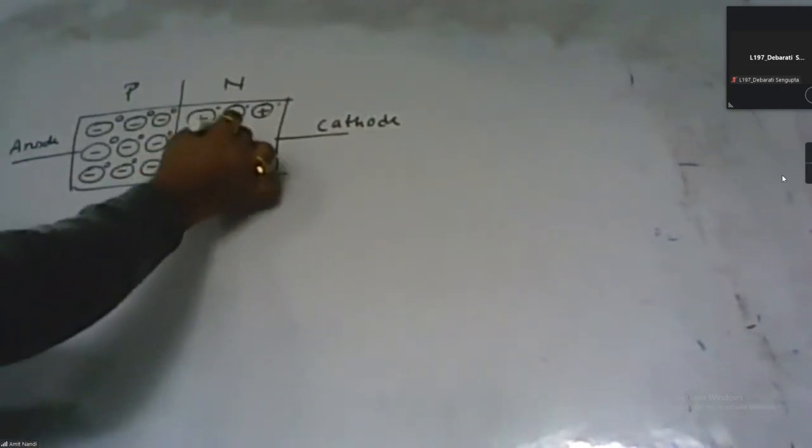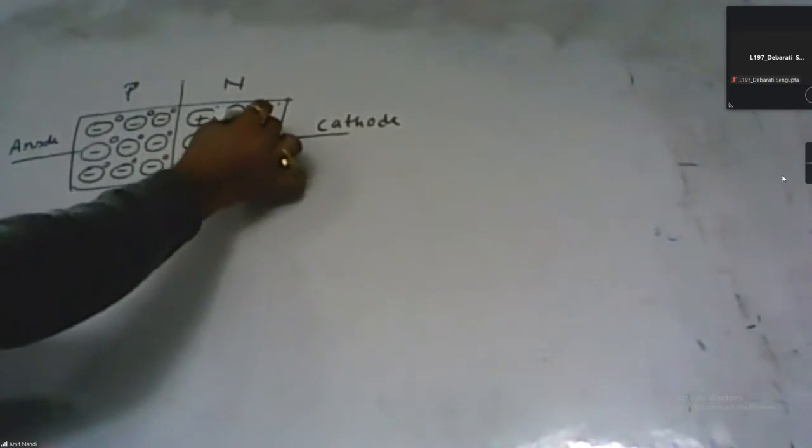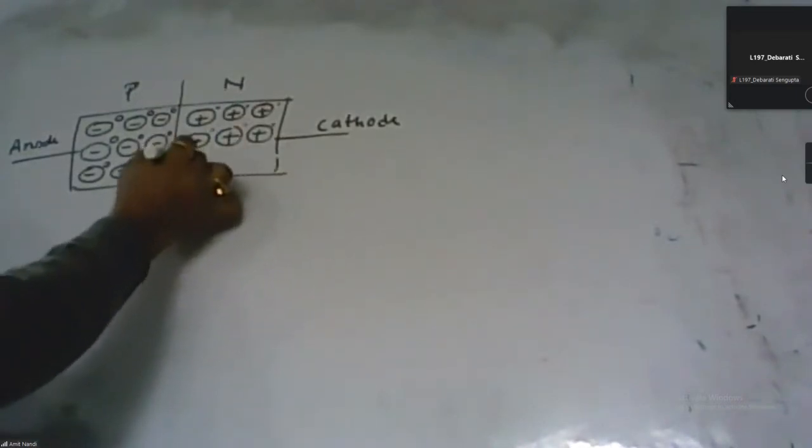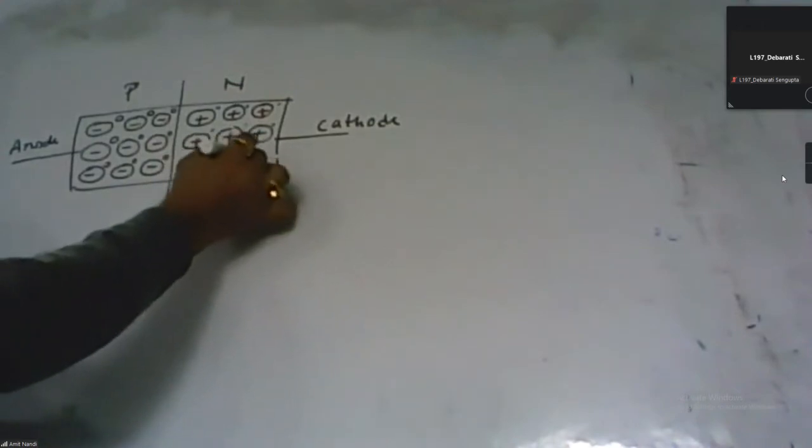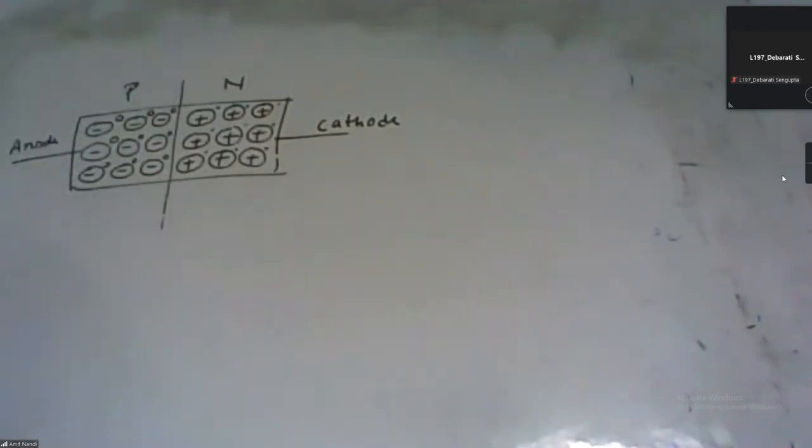So n-type semiconductor can be represented by a donor ion and a free electron. This 5th electron in the outermost orbit can be detached from the parent atom, and then the atom behaves like a positively charged donor ion. When it is a positively charged donor ion, it generates a free electron in the semiconductor material. So p-type and n-type semiconductor can be represented in that way.